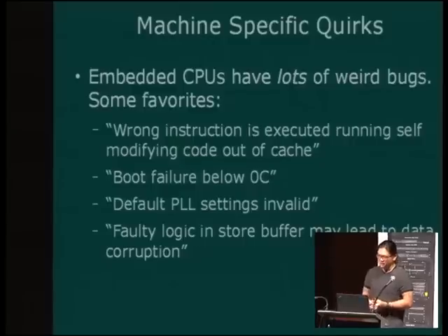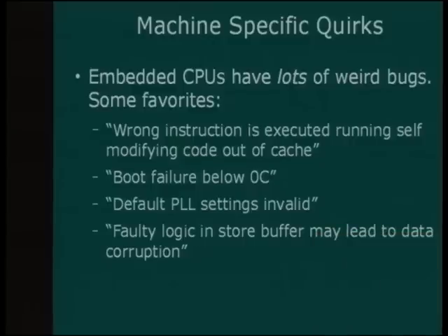Or another one here, faulty logic and store buffer may lead to data corruption. Again, no good. And the fix to this one was again in the bootloader: we had to turn off store buffer optimization. So a lot of these really bizarre quirks make porting to a particular product rather difficult.